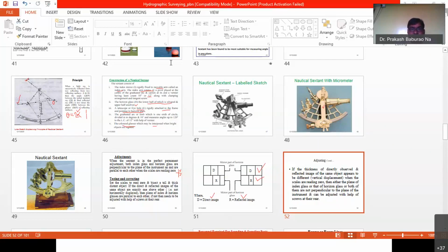Our students did this exercise, and analytically, by applying this, they observed the distance from the boat point to the shore point, P to A. P is the boat point and A is located on the shore side. That is 22.7 meters, and by the graphical method they observed 26.2 meters. Also, by the intersection method, they obtained 26.8 meters.